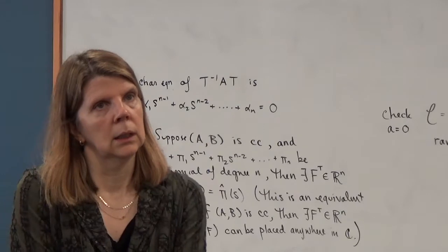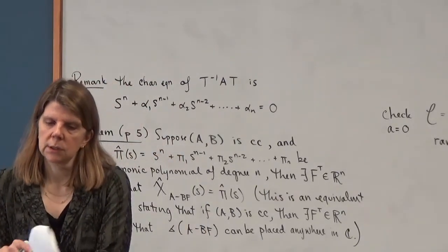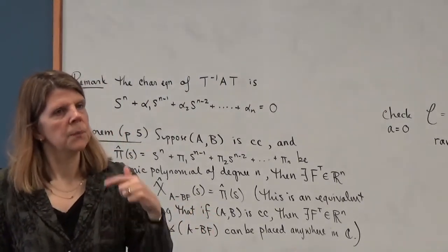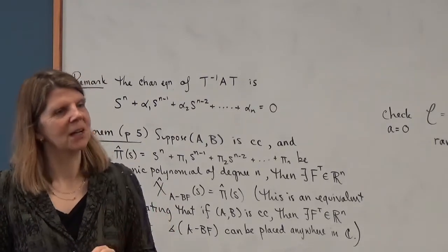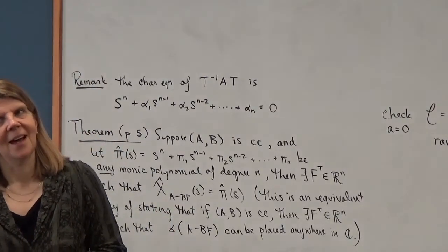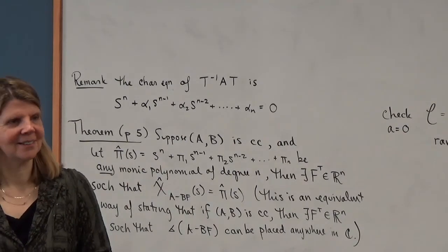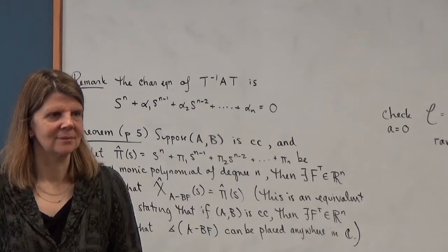Question? Will you ever be interested in shaping the closed loop dynamics into something like Jordan blocks? That's a good question. So the question is, would you be interested in choosing your feedback matrix F so that A minus BF is already in some kind of canonical nice form, like a Jordan block form? I don't think so. Or diagonal? I mean, if you're making the closed loop dynamics non-diagonalizable, so there's a polynomial